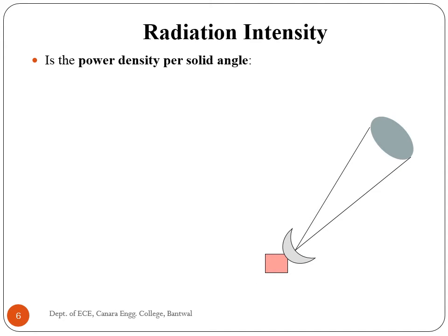Radiation intensity. Radiation intensity or the antenna power pattern in a given direction is defined as the power radiated from an antenna per unit solid angle. The radiation intensity is a far field parameter which can be obtained by simply multiplying the radiation power density by the square distance.